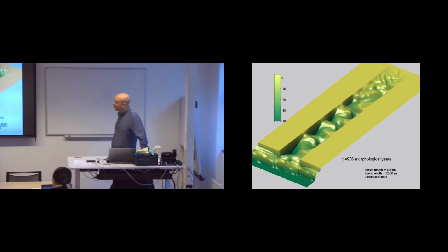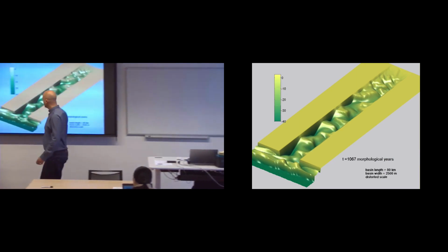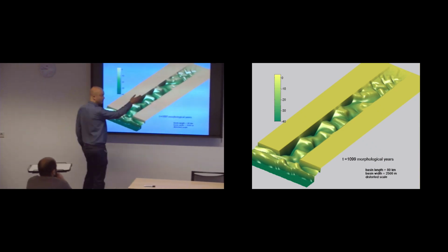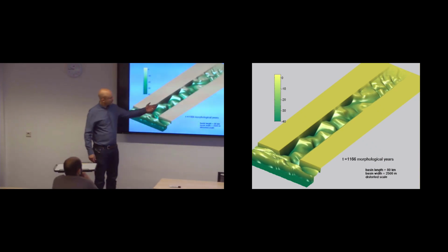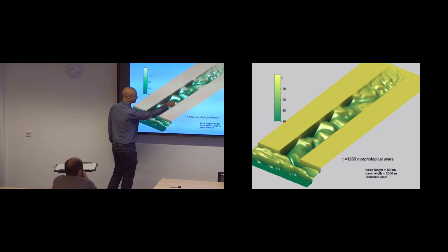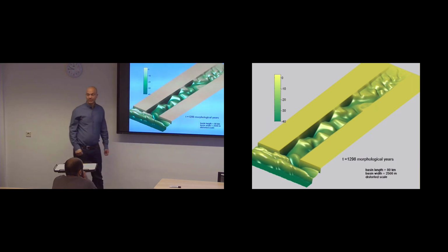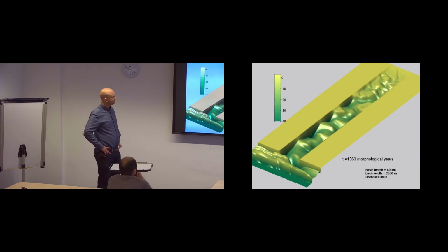Is this the effect of the river and the tidal effect, or the tidal only? Tidal. So basically what this model does is, for 1,000 years, doing a tide back and forth. And then in interaction with the sediment, it shapes this morphology. You see a nice alternating bar pattern now there. That's also happening in tides. You see it in rivers too, but also here.